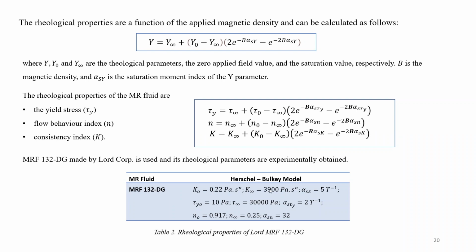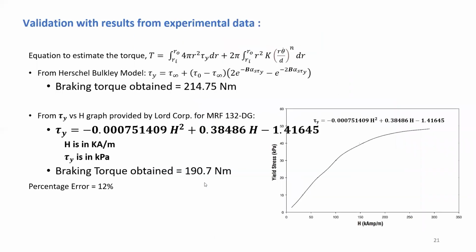Just for modeling's sake, because all these constants are not available to us, we just used their constants to see whether our software and our modeling are working properly. We also modeled using the Herschel-Bulkley model, using the equation I showed earlier for section 1, section 2 and the middle section. Using the Herschel-Bulkley model, we have obtained the braking torque around